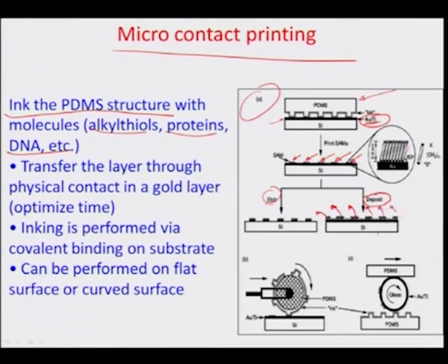Typically, this process has been a linearized process, but then many intelligent modifications have been made. For example, in this particular case, the throughput of a process can be increased by coating the SAMs on a circular cylinder rather than a straight surface, and then rotating the cylinder every time, so that it walks over this wafer containing the gold titanium film, and it keeps on creating a big array of these molecules, and the molecules can be fed every time it moves through or rotates through the gold titanium layer.